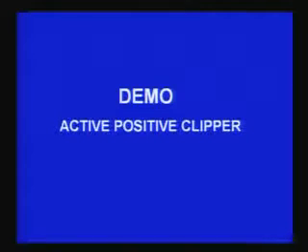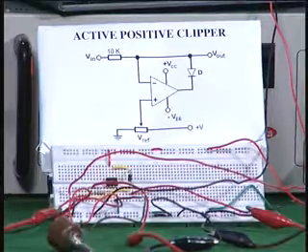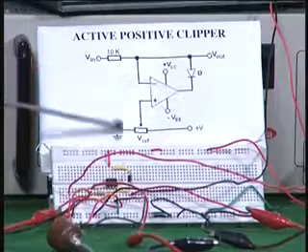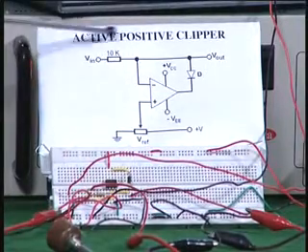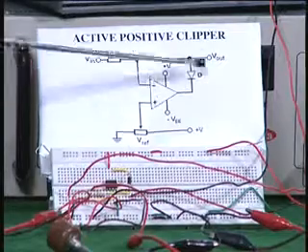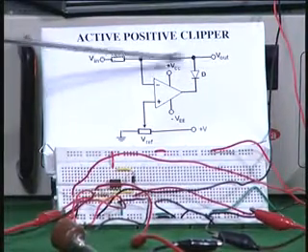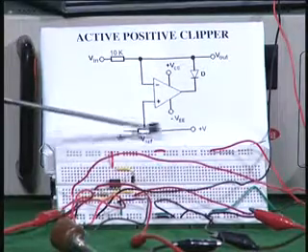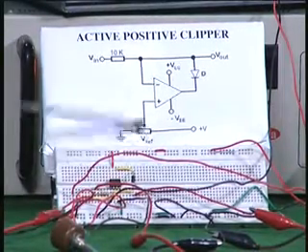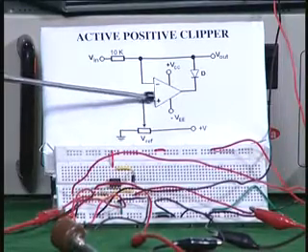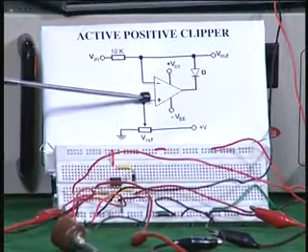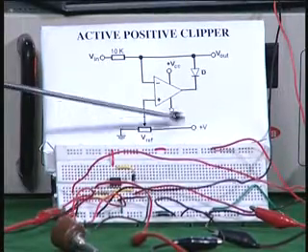Now I will show you a simple circuit, the same circuit implemented for a positive clipper. So the circuit here is the same as what I just now discussed as an active positive clipper. You have an op amp, you have the diode, and you have this signal input here, you take the output, and on this side you have got a potentiometer. The wiper of the potentiometer is providing the reference voltage for the positive terminal, or the non-inverting terminal, of the operational amplifier. This is a plus.